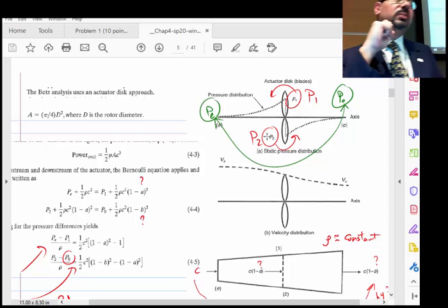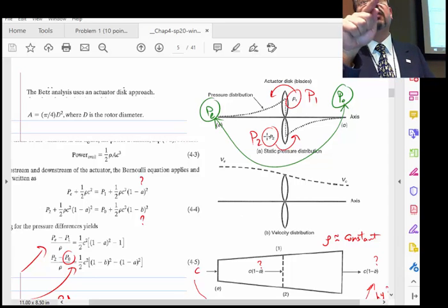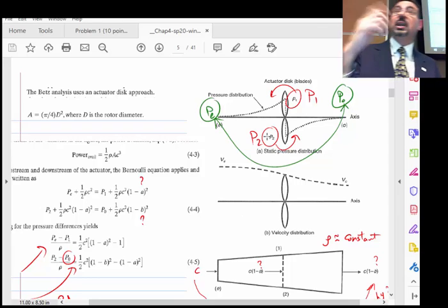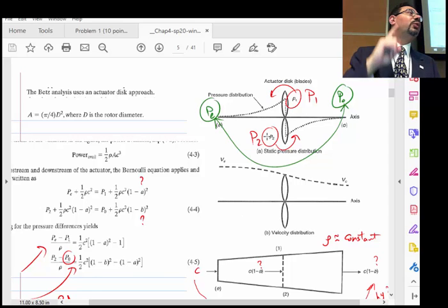Yeah, how do you find the maximum? Mathematically, how do you find the maximum? You take the derivative with respect to whatever that thing is that's changing or controlling it, and set it equal to 0. And then that is the optimum parameter. Just like in the Pelton wheel last week, when we said here's the power as a function of u, and we set the derivative to 0, and we figure out our u should be V1 over 2. That's the maximum power.